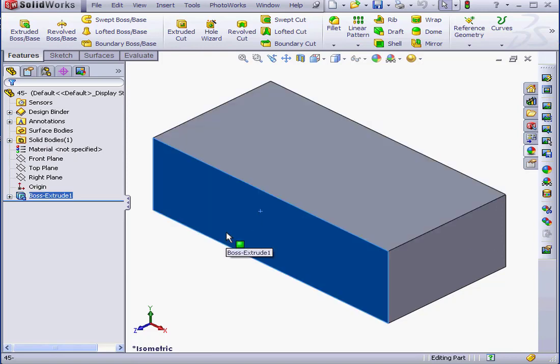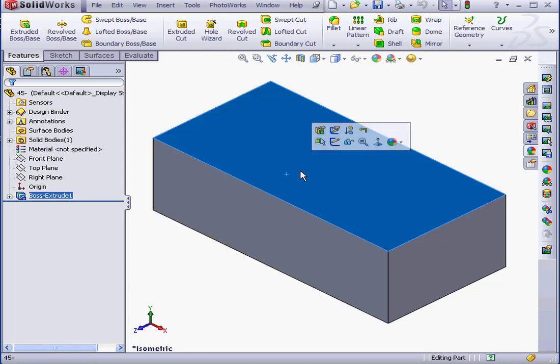Let me say a couple words about the image size first. The side that I just selected now is 1100 by 550 millimeters. The image that I've created for this face is also of the same ratio, 1100 by 550 pixels. In other words, the image that I've created is proportional to the side that I'm going to apply it to as a decal, and this is what's going to prevent image distortion when you're using this function.